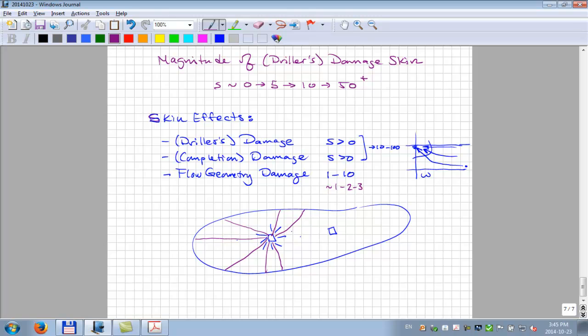Okay, but that extra pressure drop maybe said you needed 1 extra well to get the same total production, but you needed 1 less platform. So it was a huge economic success, the design of this, what they called cluster development. So basically you cluster all the wells around one spot, you get this convergent flow. It's non-ideal compared with equally spaced, but the effect is not a very large negative effect, and the added savings of having only 2 platforms instead of 3 was huge. So that's another flow geometry damage. But there's a number of these that I'm not going to go into, but there are others.